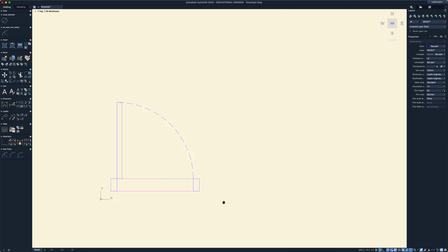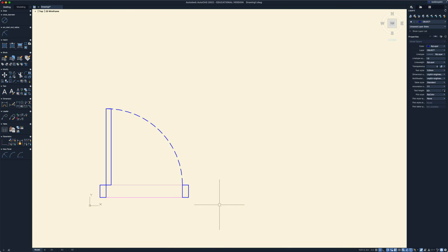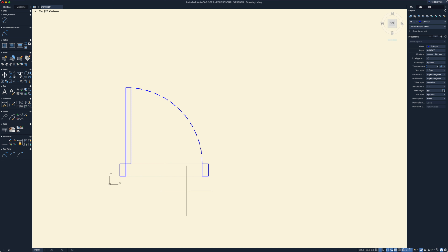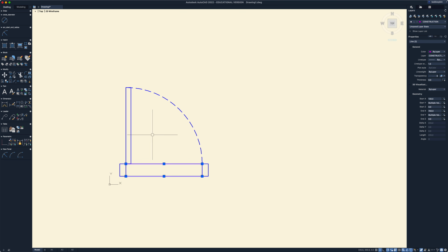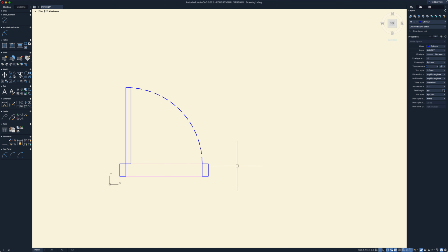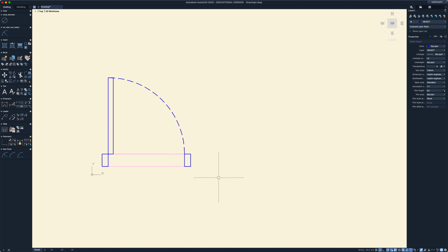And now what you need to do is make the other doors, which will be 712 millimeters, 762, 814, 864, and 916. So the only thing that's going to be different in there is basically that opening size, the length of this door, and the radius on this arc. But everything else will be the same. So I can just copy that and I'll move it over to say here. So I'll go over 600.